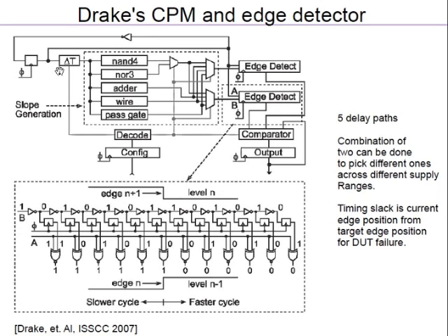And again, the idea is the same. You launch it, and then they have this configuration capability. Which one do they choose? Do they choose adders? Maybe different designs have different mixes. If it's a filter type design, it has more multiply accumulates and so on. Again, it's a trade-off. If you put in a complete multiply accumulate, it will mimic the actual multiply accumulate much better, but then you have spent so much area. So you have to be smart to use as little area as possible, while at the same time being reasonably close to what you're making.